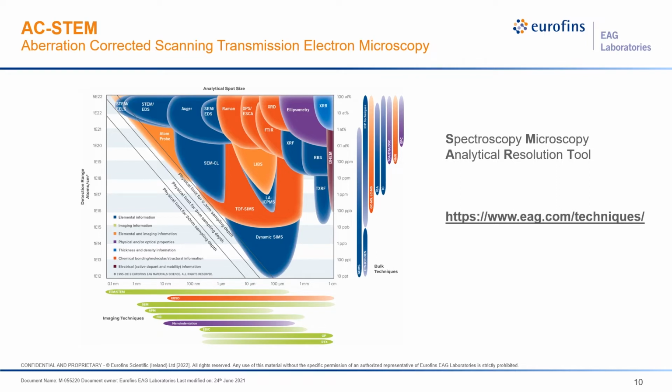And so, as I mentioned, using SIMS to look at dilute constituents or dopant level things, you can see that dynamic SIMS has amazing sensitivities down to 1e12 in some cases, but ultimately the spatial resolution really doesn't get much better than maybe a couple microns, right? So at times when you're searching for very small features, dynamic SIMS isn't going to really help you understand what's going on in that small scale.